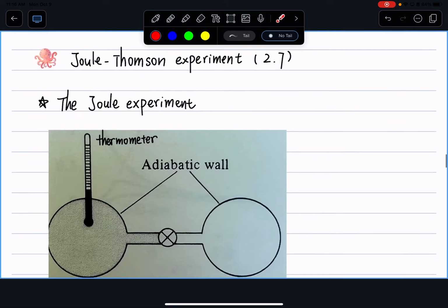Now, we don't have an easy way to measure the internal energy of your tank of gas. So this internal pressure is something that you can't directly measure, but you can derive it from our Joule coefficient and also the heat capacities, right? So again, the power of thermodynamics is that we give you information about things that we cannot directly measure, but we can link that property, like internal pressure, with some of the coefficients we can measure, and you get an understanding about the relationship between the internal energy and volume and temperature, etc.